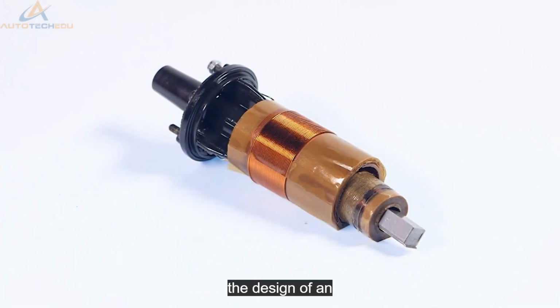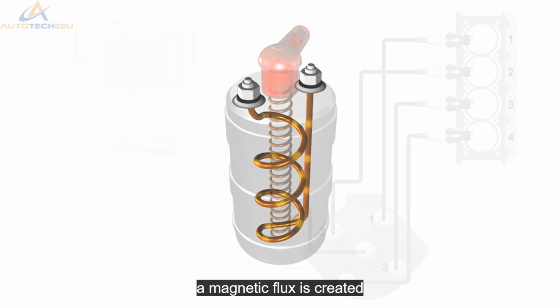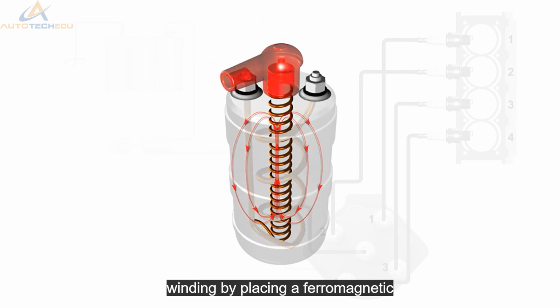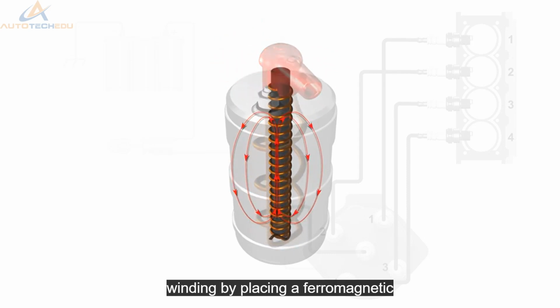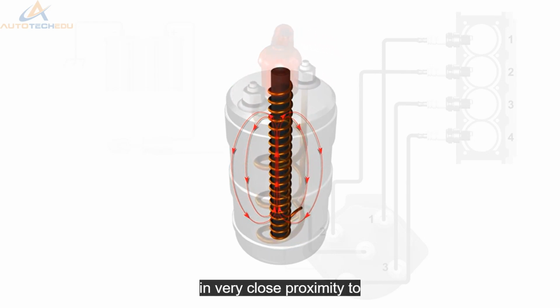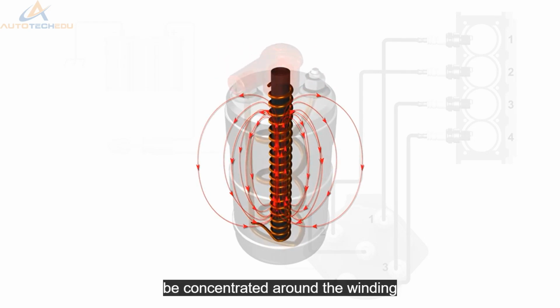The design of an ignition coil puts the primary and secondary windings in very close proximity, but they are separated by an insulating material. When current flows through the primary windings, a magnetic flux is created and expands across the secondary windings. By placing a ferromagnetic material, such as soft iron, in very close proximity to the primary and secondary windings, the magnetic flux can be concentrated around the windings.